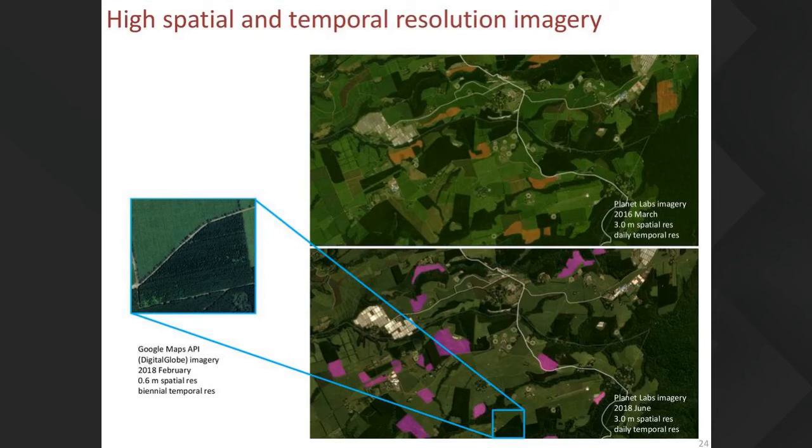And in practice, in a lot of cases that we look at, there's more greenfield type planning, which is a lot easier, where you just basically assume that the customers that you're connecting aren't going to be connected to that existing low voltage line, and maybe that they would then connect to a medium voltage line, or there would be a medium voltage extension to go to a new cluster.